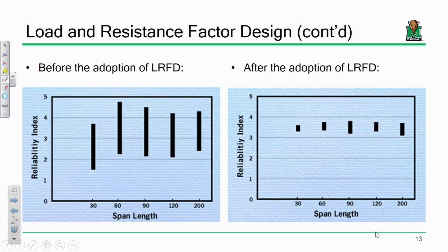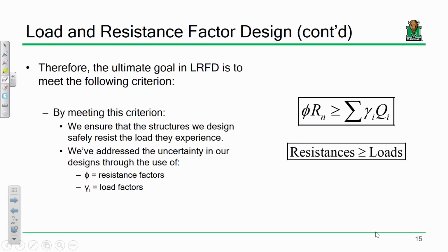The philosophy that we use, LRFD, sometimes called ultimate strength design, helps to ensure not a perfectly safe structure, but structures with low and uniform probabilities of failure. That's the idea. So what we would do is adjust the resistances by these resistance factors. These are lowercase phi values, and we'll discuss those later. Then we adjust our loads with various load factors as well. And all of those values are these quote-unquote magic numbers that adjust these loads and resistances such that we get uniform levels of safety.